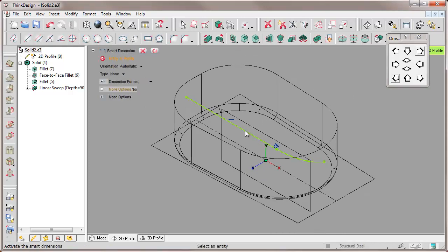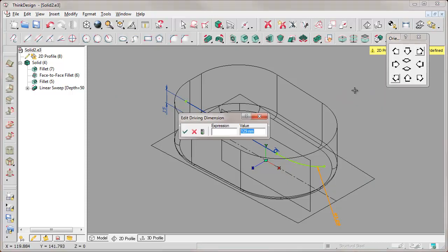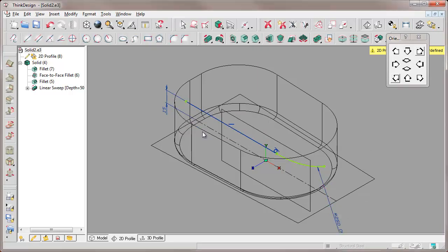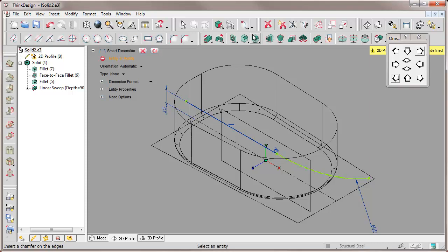Now we insert the dimension constraints to manage the distance between the line of this profile and the axis of the base profile. We set it to 15. We set the radius of the arc to 250 using the Edit Driving Dimension command. Then, we set also the distance between the endpoint of the profile axis and the tangent point between line and tangent arc of this profile.